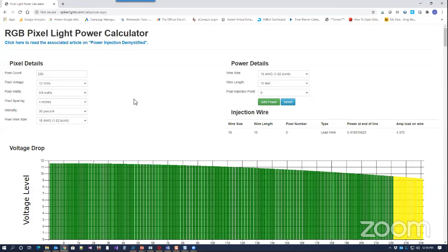And I use this kind of as a gauge to say, where am I pushing my limits? Am I overdriving a receiver board, or do I need to split power up because the power supply itself can't handle it? And even though I set my display at 30%, I've overloaded it with 40 amps at 30%. So it's never going to be actual 30%. Okay. I hope that answered the question, or I confused it even more.